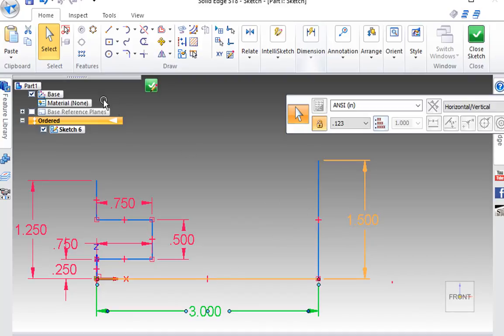And when I say parameters, a couple of the parameters we've been drawing with that you don't know about, this plus sign means the line is horizontal or vertical, and you'll see them in various places. This red square means that these two lines are touching at a point, and that's very important because we need to know that our sketch is connected all the way through. So those are parameters that we're building up, dimensions and geometric relationships, as we build the part. So now we'll get more into that, but just wanted to let you know that's happening and that you can put in dimensions and change them, and the part will resize.